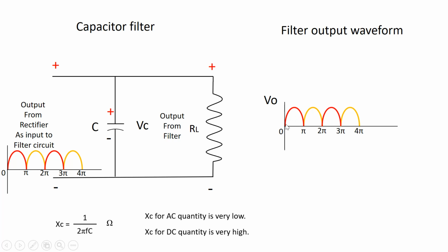voltage is applied. Along the same line, the voltage of the capacitor rises up to this peak value, which can be named by some letter in the waveform. The charging and discharging sequences can be seen by these green lines in the graph, wherein it charges suddenly, instantly along with the applied voltage up to this peak. From this peak, it starts discharging through this load resistance.